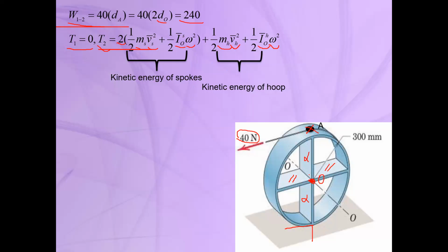But it will be a little complicated, because if you want to obtain the mass moment of inertia about the center C, you should transfer both of the mass moments of inertia to this point, and it will increase the number of calculations. So here we can use this equation about the mass center.